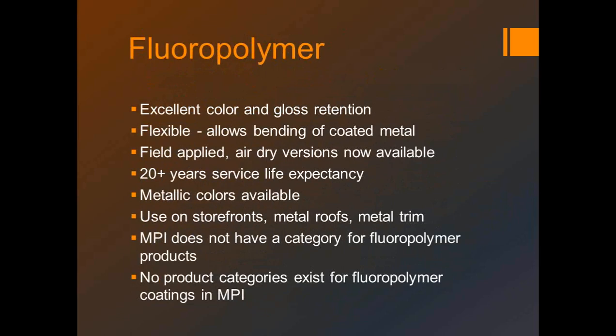But when it comes to cost per square foot per year of service, these products have a really good story to tell. A lot of times paint gets looked at on cost per gallon, and you are looking at a significant cost per gallon for fluoropolymer, but you're also looking at a significant life expectancy. So if you don't want to have to go back in there and do much maintenance for 20 plus years, then fluoropolymer systems would be a good thing to look at.